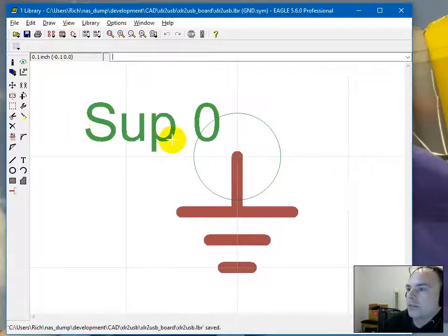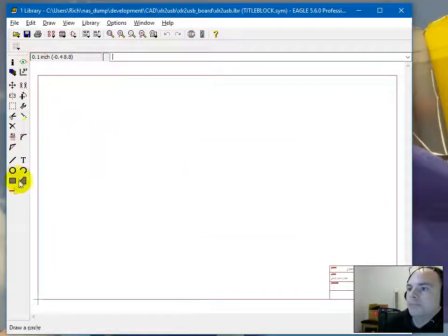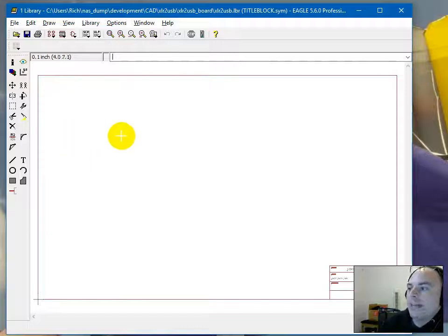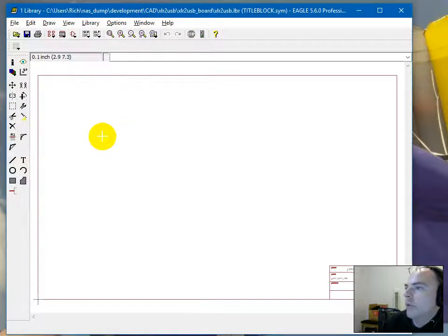One interesting side effect about supply lines is if you have a pin that is set up, let's grab a, well, I'm in it. Oh, okay. Title block maybe? Nah, it doesn't like that. I'll explain in just a second what's happening. What's happening is you've used a symbol in a part, right? These are all active parts. Their symbols are being used, and you can edit things. You can move them around, but you can't delete a pin that's in use, and you can't add new pins.